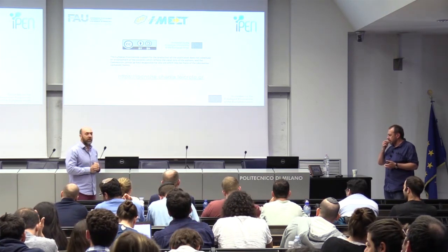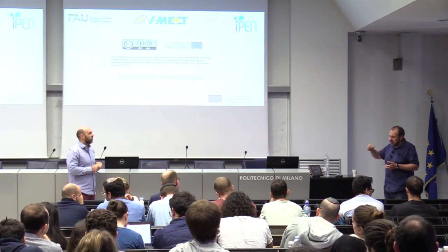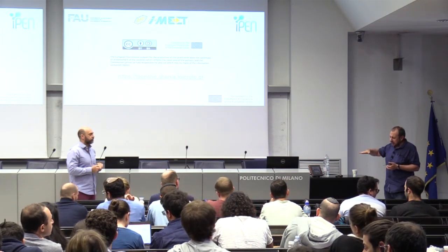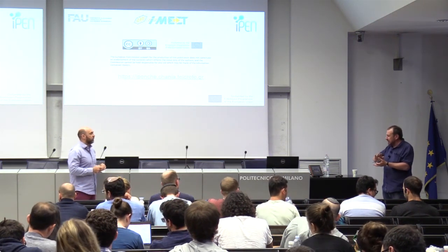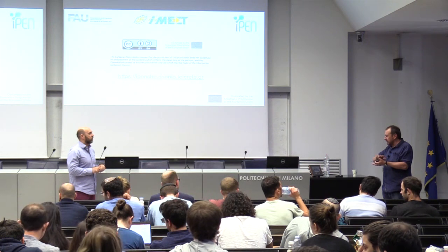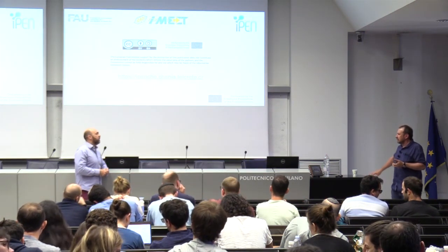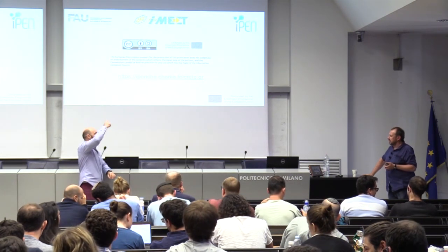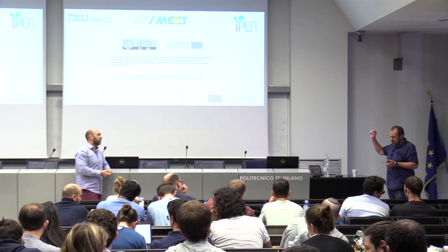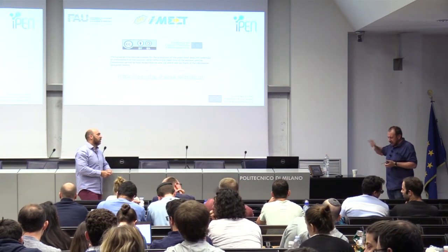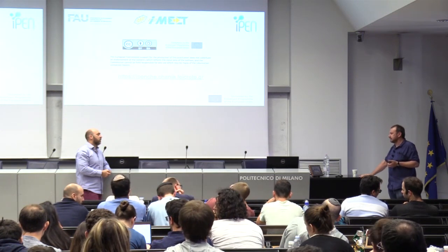Concerning once more this laminated example, you could do the P3 before you do the lamination, you could cut the P3 and then put it together. But it would be very tricky to put it together exactly, because the P1, P2 and P3 have to be close enough. The P1, P2 and P3 lines? Tens of microns. By the beam waist of your laser? Yes, the beam waist in one of these examples was something like 20 microns, in another one 35, or this order of magnitude.